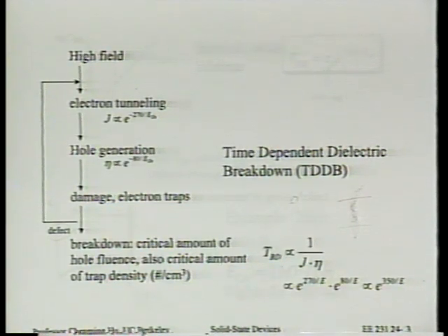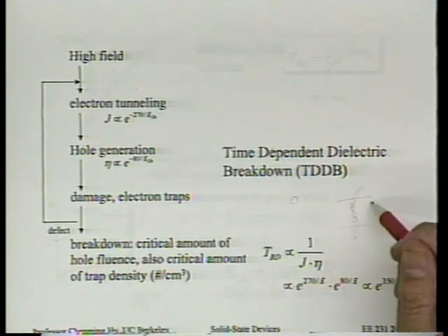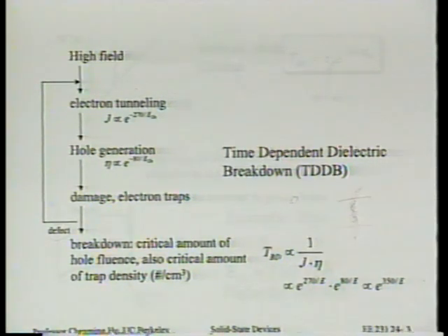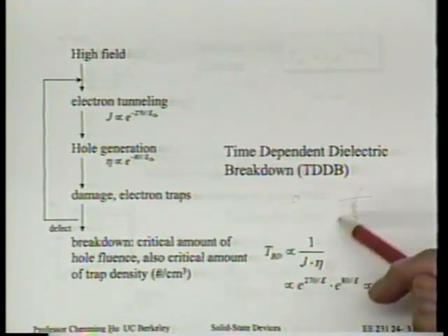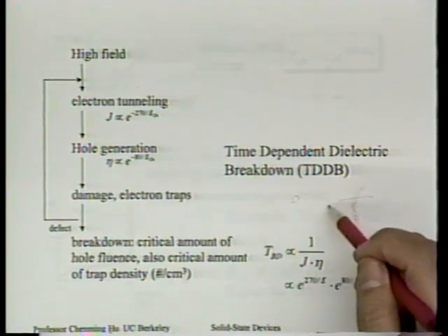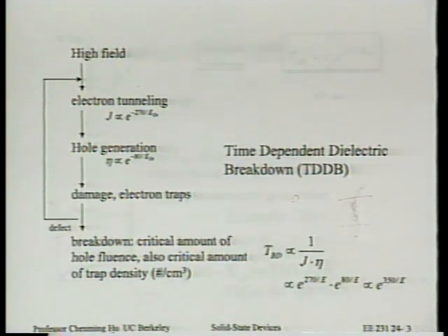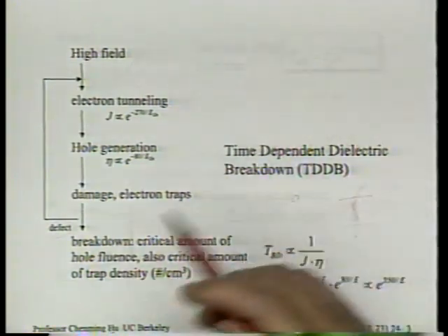Something that's very difficult to predict, but we can assume it probably has to do with a location that has weaker bonds around it. Whether it's because of some very gross defect, a piece of airborne contaminant that happens to land on that spot of the wafer, or simply because the amorphous SiO2, being pseudo-random, happens to have one spot that's a little weaker than the other spots, always one spot will break down first. Just remember that. And we can say more about this later on.